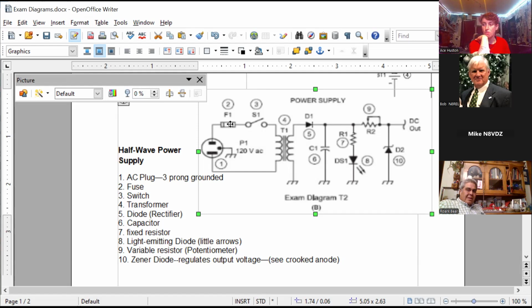There's cylindrical fuses, or the automotive type fuses with little blades, but you can see the little loop of wire, and you can see whether or not the fuse has been melted or not. When a fuse goes, it goes. If you have a circuit breaker, it's kind of a switch that operates on high temperature, but once it cools down, you can reset it and use it over. So it costs a lot more initially, but it's worth it.